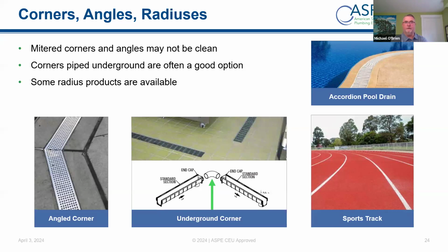So even things like a basket that sits inside of a trench drain in an area where they're making breaded meats, for instance. Any of that bread material that gets on the floor, you want to try and collect it before it dissolves in your wastewater, because it can lead to some pretty expensive surcharges. So we have baskets that sit inside the trench drain, and anything that makes it into the channel gets supported by that basket up and out of the flow of water, so that you can dispose of it as a solid.